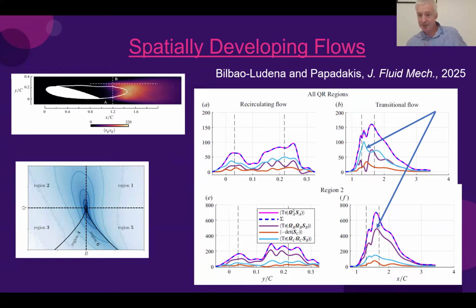And you can actually start to then see why perhaps equilibrium turbulence models might start breaking down for these kinds of problems. Because if you look at this, there's a spatial separation between how these terms are contributing to these dynamics that will be difficult to accommodate with a conventional turbulence closure. Hence, this is DNS.